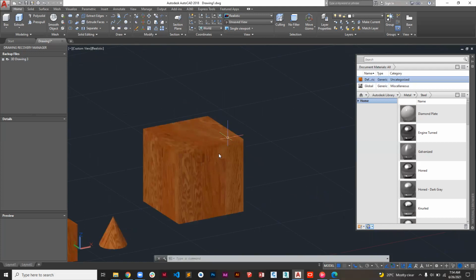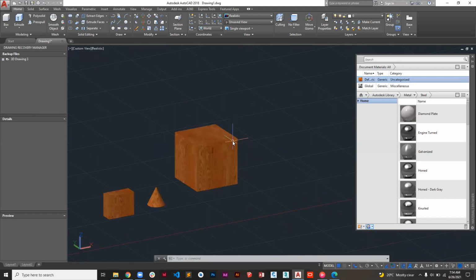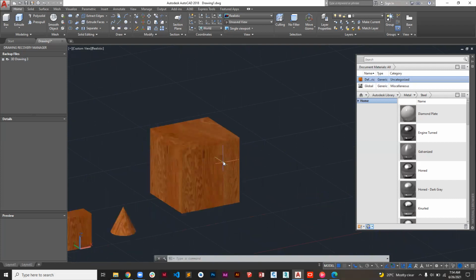Is there any repetition? It's just one tile on each face. Yeah, because I've used the same scale, so that's what we wanted to see. When I went to scale, I set it to 9 by 9, and I also drew a box of 9 by 9. So when you apply, it just matches the scale, meaning that the scale is very important.